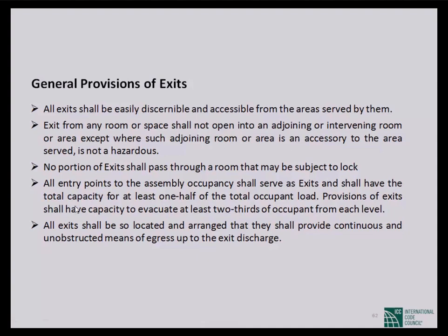Provision of exits shall have the capacity to evacuate at least one third of the occupants from each level. Before, it said from the same floor; now it is saying different floors. Particularly in assemblies, two or three floors are accommodated. In theaters and auditoriums, they use different levels for construction.